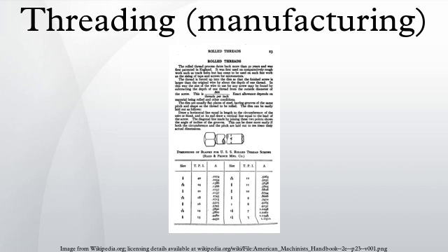Cast threads in metal parts may be finished by machining, or may be left in the as-cast state. Whether or not to bother with the additional expense of a machining operation depends on the application. For parts where the extra precision and surface finish is not strictly necessary, the machining is foregone in order to achieve a lower cost. With sandcasting parts, this means a rather rough finish. But with molded plastic or die-cast metal, the threads can be very nice indeed straight from the mold or die. A common example of molded plastic threads is on soda bottles. A common example of die-cast threads is on cable glands.